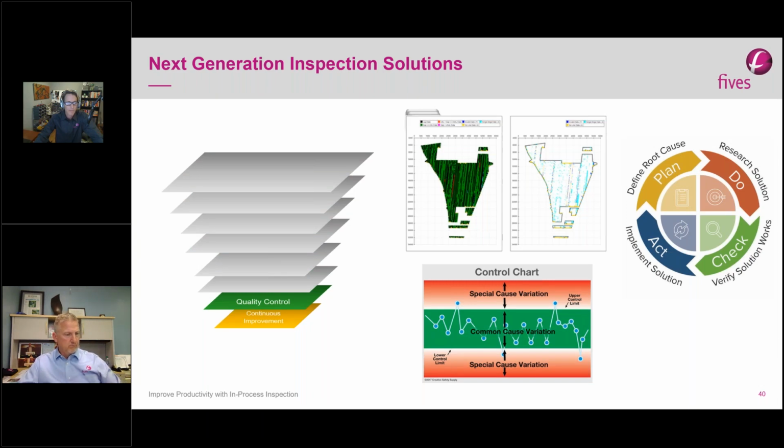So we're getting to the end. The last piece is to report the results. If there's no rework, we move on. If there's some rework, how do you describe to the operator how to do the rework efficiently, giving them a task list? And then there's a lot of opportunity around this data for statistical process control and corrective actions, right? If you find defects that all have familiar patterns, we've worked a lot with being able to correct the program, correct the machine, correct the process. There are all the different aspects that need to go through the formal corrective action process.